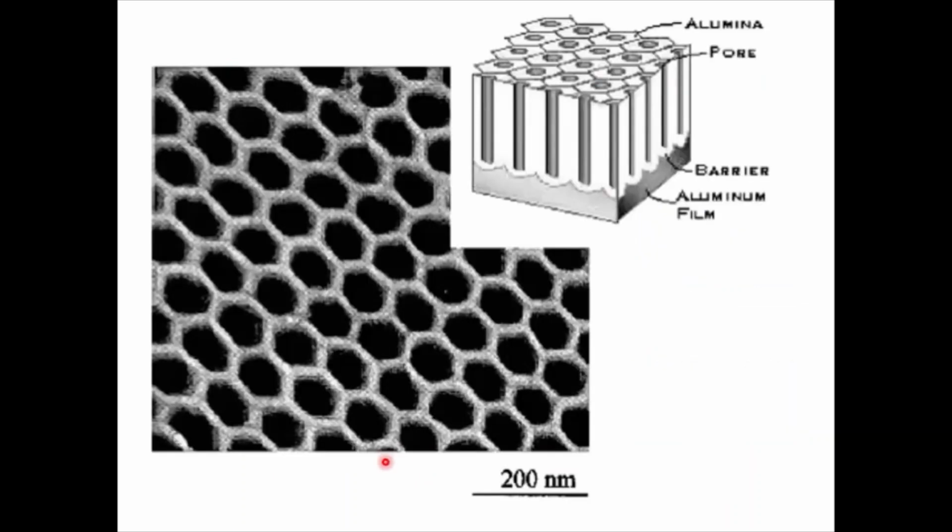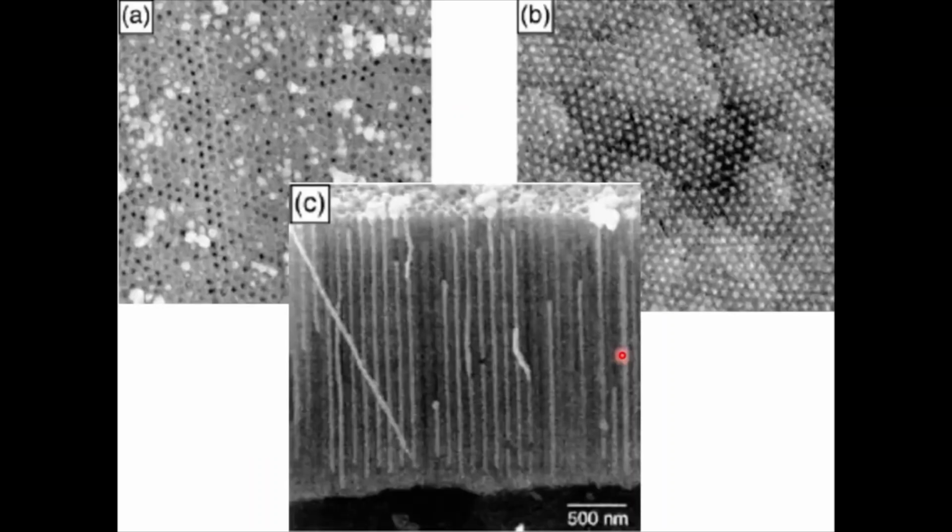So this is one kind of aluminum oxide, all right, anodized aluminum oxide, with a honeycomb-like structure, where we have deposited cadmium telluride by using an electrochemical process, cadmium chloride as the cadmium source, tellurium dioxide dissolved in hydrochloric acid as the tellurium source, adjusting the pH close to acidic, right, and we are able to get freestanding nanowires. These are almost 2 micron in length, freestanding nanowires of thickness around 50 nanometer. This is cadmium telluride in an anodic aluminum template.